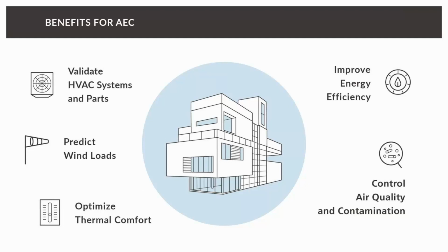And we can use simulation, fluid flow simulation, not only to improve, for example, the design of a fan to increase the flow rate, or to increase the performance of a ducting system to decrease the pressure drop, but we can also use simulation to really understand how our HVAC system and its elements are interacting with the room we want to ventilate.